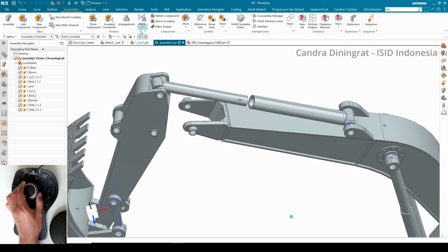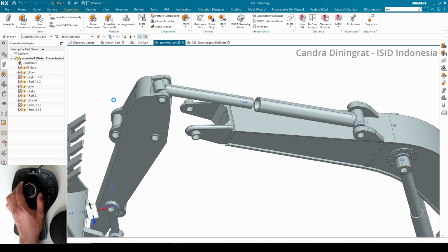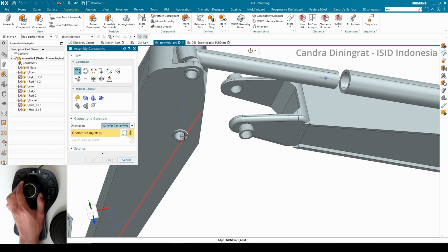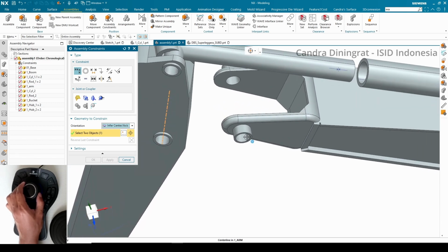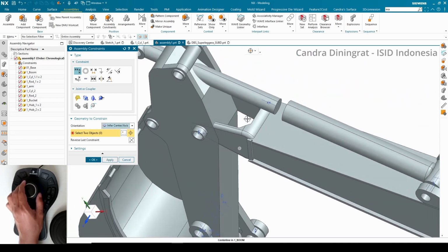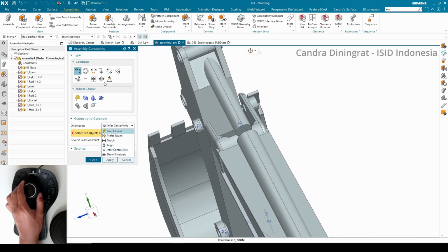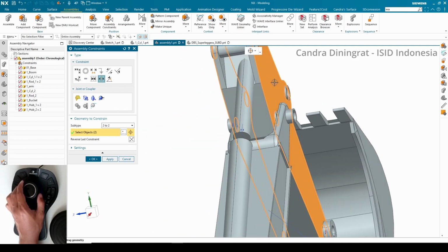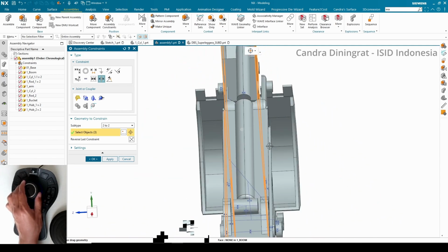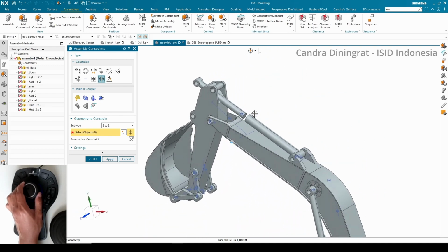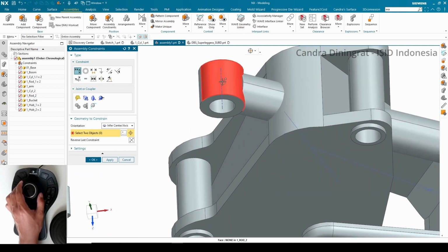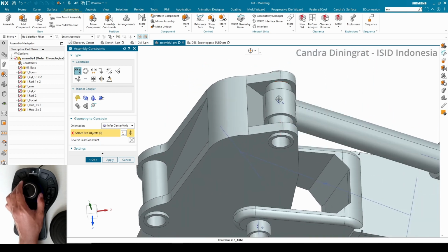and let's connect it again using this assembly constraint, infer axis between this axis to this axis, and do a center again in these two faces to these two faces. Okay, and we can connect this axis again like that.